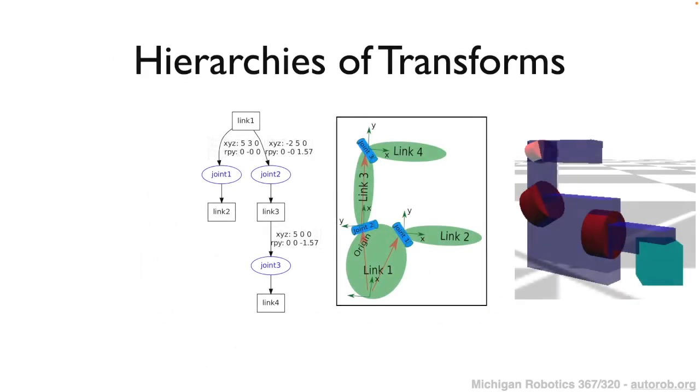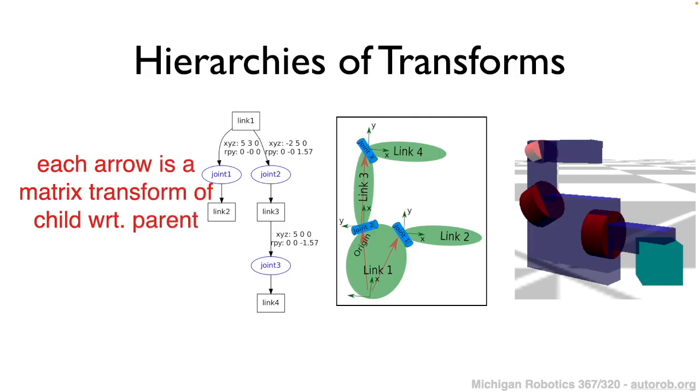The other thing we are going to talk about now is how we can use this notion of composing transformations to build up our hierarchy of transformations used for forward kinematics. We're going to step through how we can construct our example robot by traversing the kinematic tree that defines the robot and composing transformations along the way, in order to position each link and each joint within the world coordinate frame.